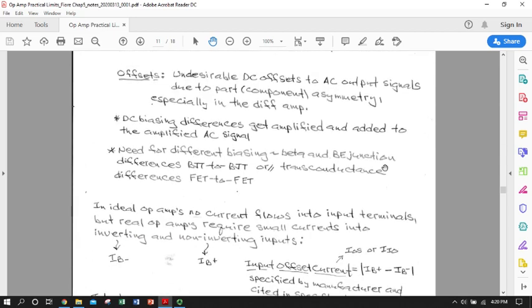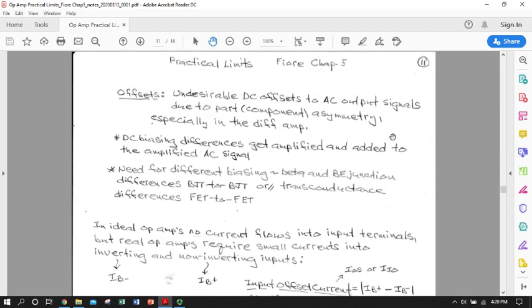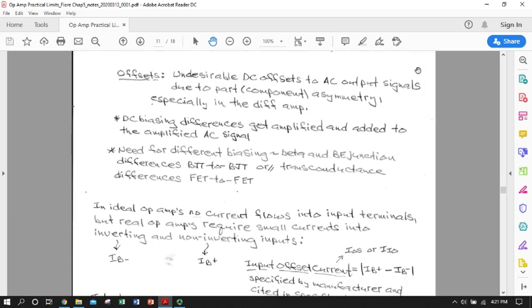Okay, we're going to end the lecture here. We'll probably have 2 more recorded lectures. We've got another 7 pages, so we've now covered all of the characteristics of real live op amps that are mainly due to that middle of the op amp compensation capacitor that controls frequency characteristics. So gain bandwidth, limits on the upper and lower end of our mid-band gain region, definitely frequency related, and then slewing rate is all about frequency. It's all about time rate of change of voltage.